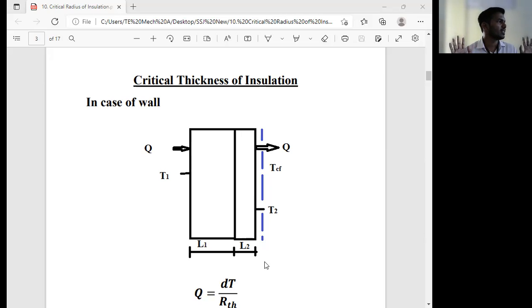If it is air or liquid, we say it will be convection; if it is solid, it will be conduction. So here 2 slabs having solid are there, therefore conduction is there, and whatever the air at the right-hand side, therefore we say that there is convection. So how many resistances will be coming? 3 resistances will be coming.